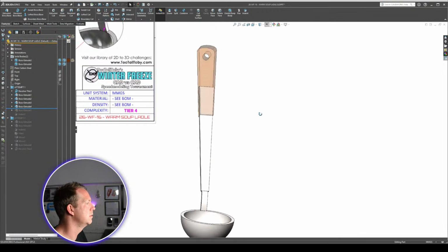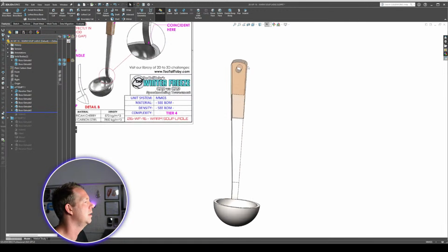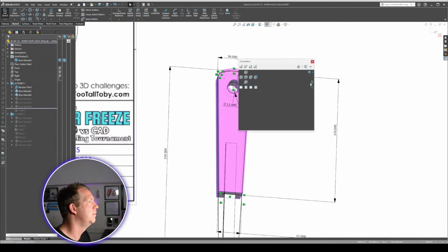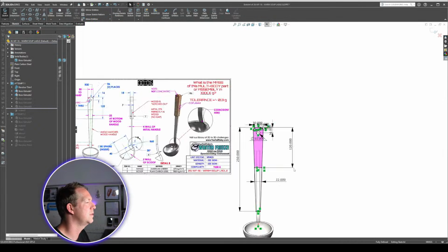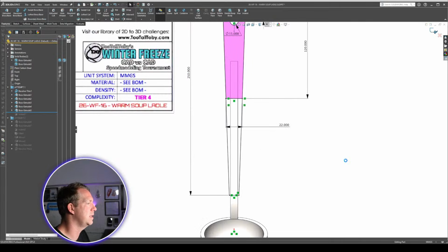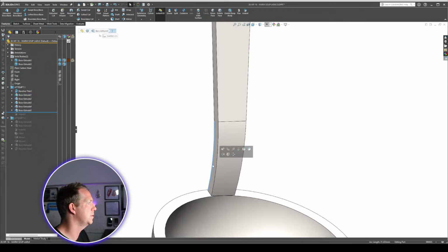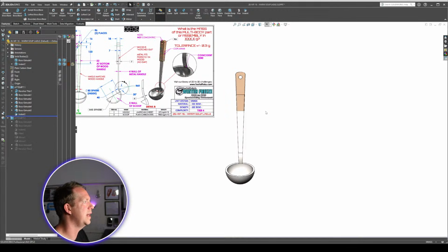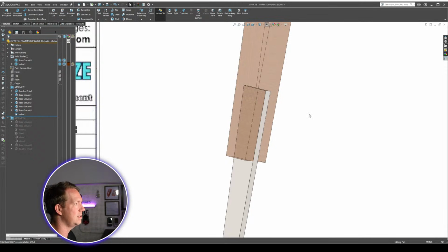I then did my angle, right? And you can see then I'm having to do another little extrude down the bottom. Now, I believe that I had this dimension correct. I've got 30 to the virtual sharp, but somewhere in this one, I've made a mistake, and I think it was down here. Yeah. This bit here, these are supposed to be parallel, not up to the face. So that's where I went wrong with this first attempt. I didn't see it until now. I did an indent at the end to remove that material, but you could just as easily, like Arte says, do a cut.